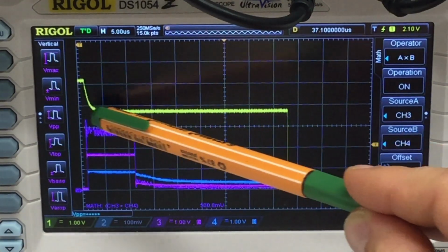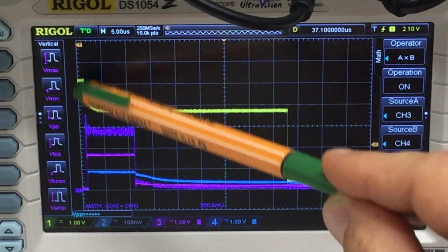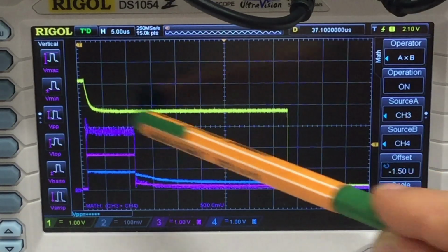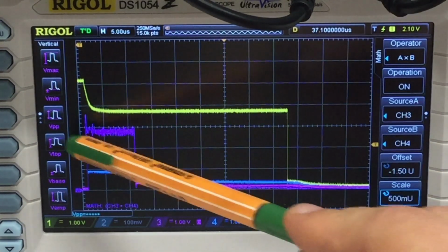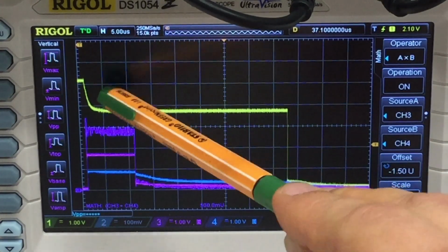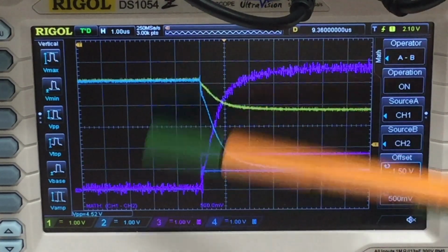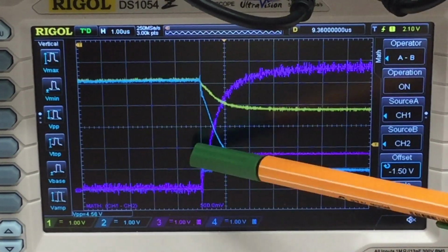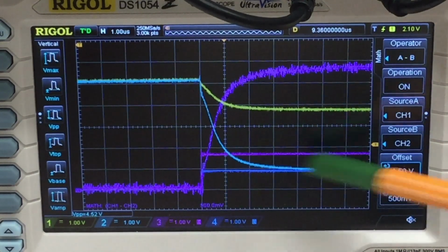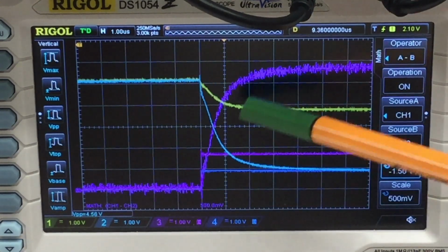But let's have a closer look here at this gradual switching on of the TRIAC. And I will now use the calculation function to actually display the current through main terminal 2. So here we are still in the off state, and these are the two probes across the gate resistors. So here comes our gate triggering pulse.